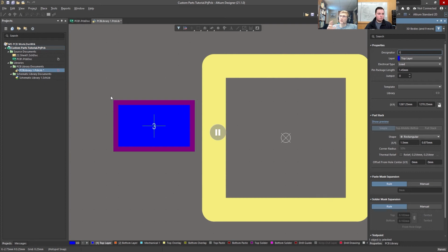There could be misalignment with the template, but more likely there's actually some expansion. So Altium tries to basically predict that expansion with some typical numbers. I think it's like 4 mil or something like that. So this edge is where they're actually going to define that mask to, and then when they do the photolithography process, Altium anticipates that the solder mask will expand inwards, and that's why we have this little region here.